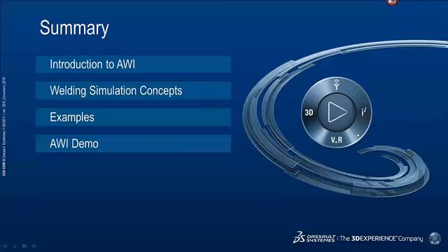But as soon as it becomes active, typically there is a big differential in the stiffness, and so if you're not careful, you will end up with a discontinuity in the stress. So our methods now address that discontinuity and make sure that the jump in the stress magnitude is avoided. And we do all that at an increment level without having to switch to a different step, which was the case for model change.